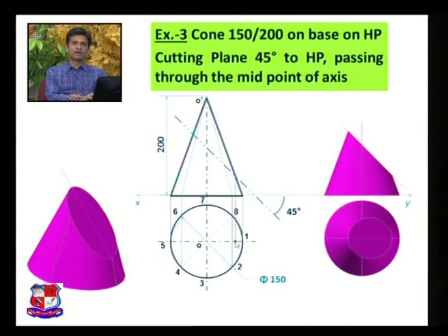So here is point number P1. With the same analogy, find out the point of intersection between this imaginary generator O2 and this cutting plane. So it would be somewhere here, and from this point draw straight vertical line like this, and that will cut O2 at this point and O8 at the same point somewhere here. Point number O4, from this point straight vertical line, it will cut O4 at this point. Similarly O5, straight vertical line from this point, it will cut O5 at this point.